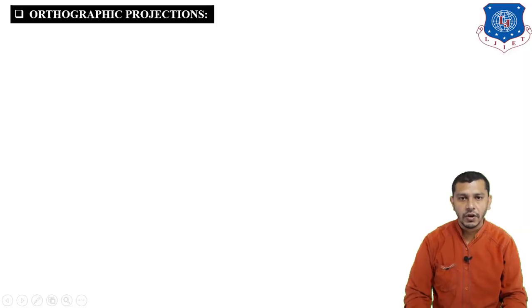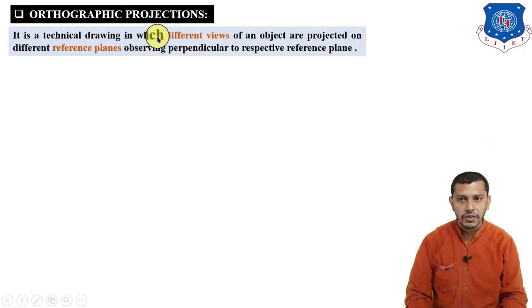So let's start with the orthographic projections. So what are orthographic projections? It is a technical drawing in which different views of an object are projected on different reference planes, observing perpendicular to the respective reference planes. And the meaning of orthographic projection is perpendicular projection, and projection means to draw the front view, top view and the side view of the given object.